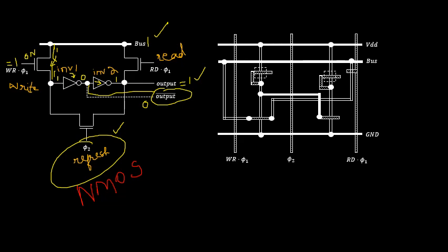So if I want to perform the refresh operation, at every clock signal of phi2, the stored bit is refreshed through the gated feedback path. This is the feedback path which is present in the circuit. So the refresh operation will be performed through the phi2 signal. That is how the refreshing will be done, and the stored bit is held.